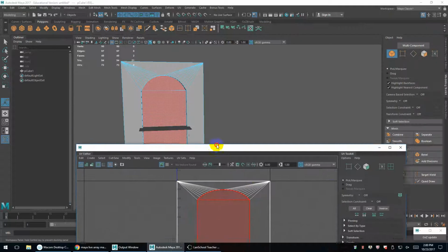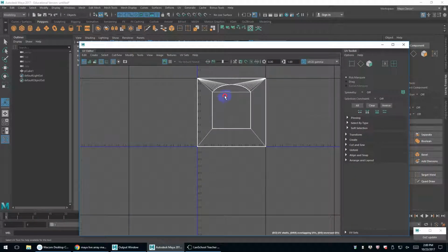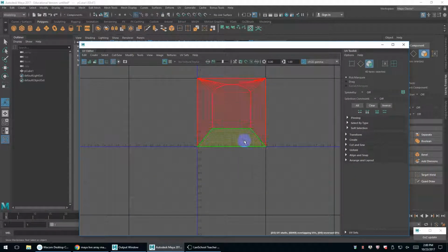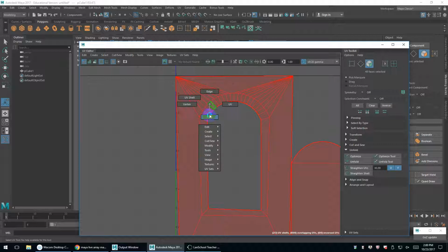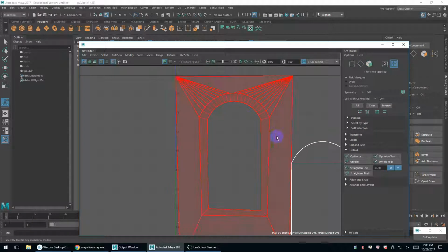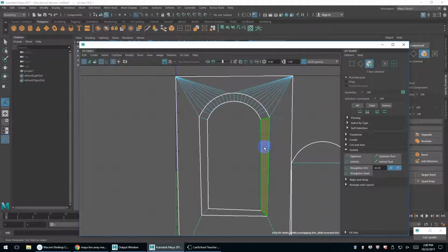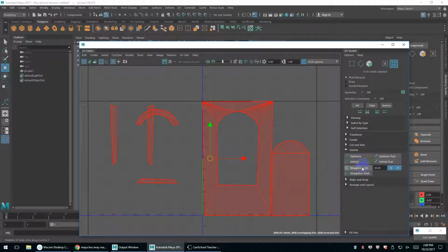Now remember, I didn't scale things. I set the proportions right. I didn't scale it, so nothing's distorted yet. I'll grab all the faces again. Let's go face. There we go. Control Shift A, unfold, and I'll try a quick unfold. And these interior edges, I usually want to split them off as well. So I'm going to shift double click around like so, create UV shell. And then I'll actually grab, again, these two faces, I'm going to break these off as well. So I'll go create UV shell. So I'm basically going to have sort of 4 islands out of that. So I'll grab everything again, unfold.